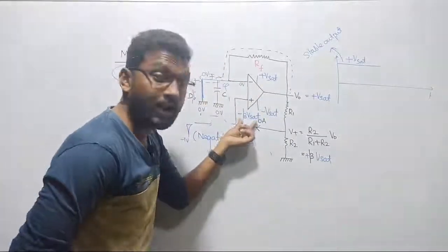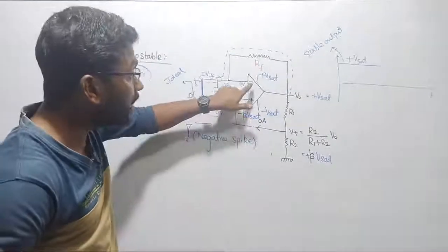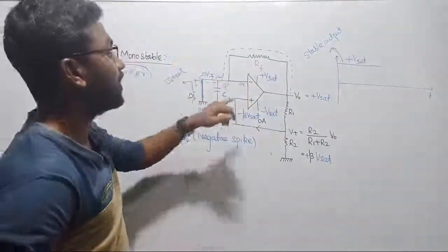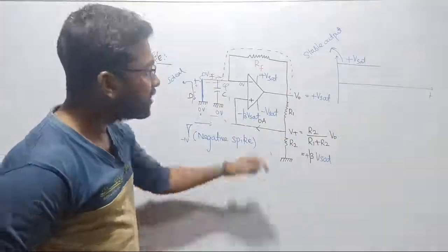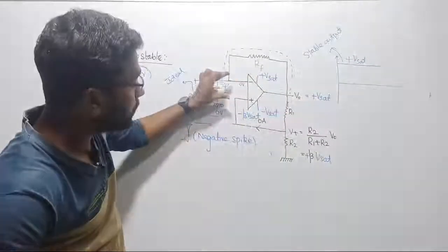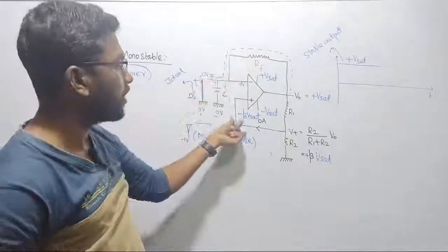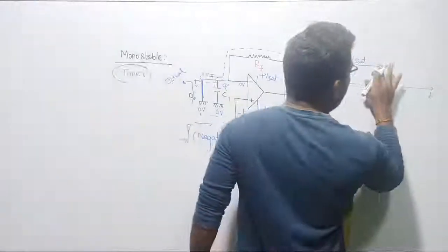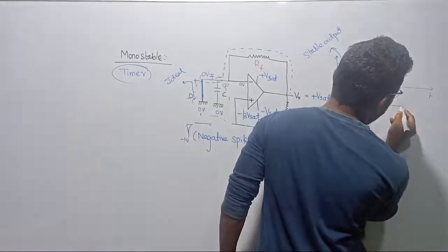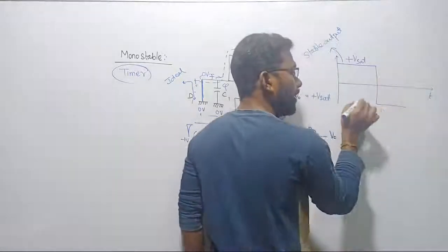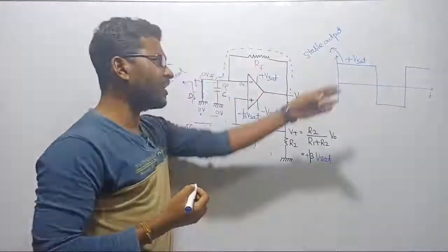It happens quickly, right? So now, just observe, sir. Here we have 0 voltage, here we have minus beta V set. When the voltage across the inverting terminal becomes greater than the voltage across the non-inverting terminal, the output of the operational amplifier will change or not? Yes, sir. What is the available voltage right now? Plus V set. Now because of this change, the inverting terminal voltage becomes greater than the non-inverting terminal voltage. So automatically the output state of the circuit will immediately change to the quasi state, and for a particular time period it remains constant, and then it gets back to the normal, stable state. And then your output won't change.